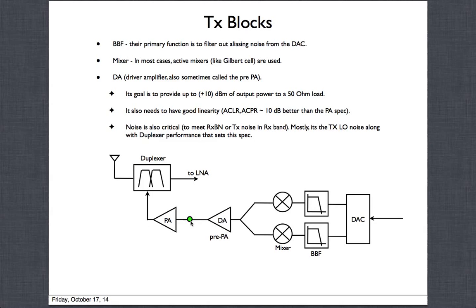So even if you provide up to say plus 4 dBm type of power, that's good enough, whether it's a GSM type 2G PA or a linear PA, it's good enough. So this power amplifier, again, as I said, it could be a 2G PA or a 3G PA, and this is something that the manufacturer, the OEM like Samsung, will actually replace. When they make a phone to support 2G, this will be a 2G PA. They will populate there. If it's not, then they will populate a 3G, right? So they make these different versions of the same, where at least you don't have to change the transceiver.